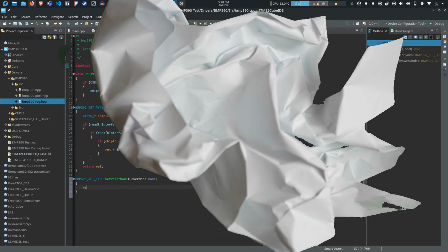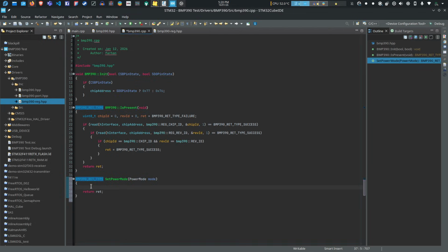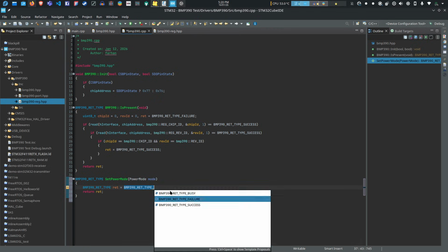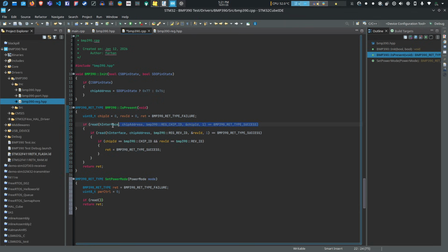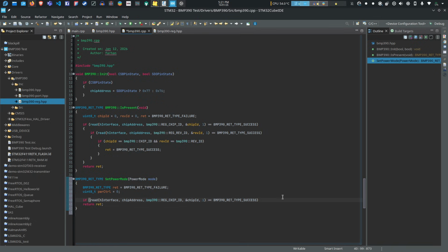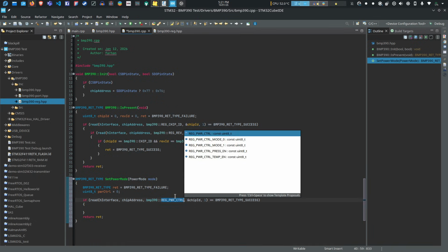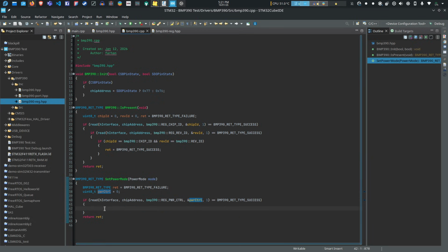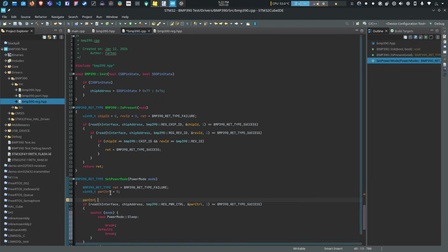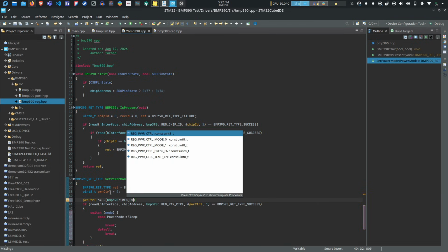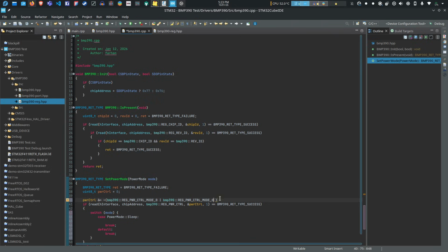And this is the method that we are going to use when the contents of a register need to be modified. Coming back to the set power mode function, I'll create a variable read to store the return code, another called PWR control set to 0 to store the contents of the control register. Now, we'll read the contents of the PWR register into the power control variable. I'll use a switch case statement to set the power mode. But first, the mode bits, that is the 4th and 5th bits in the variable, must be set to 0.